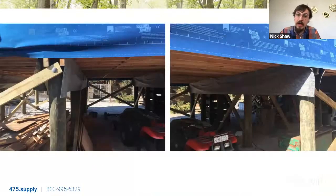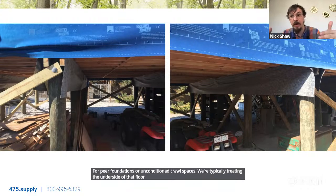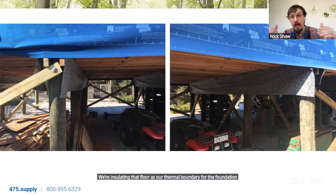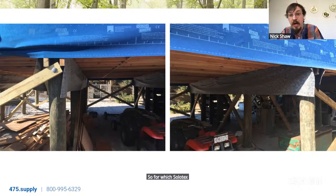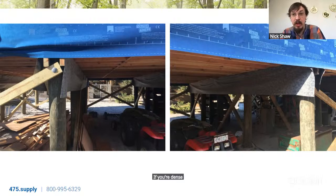For pier foundations or unconditioned crawl spaces, we're typically treating the underside of that floor system as our air barrier. We're insulating that floor. That is our thermal boundary for the foundation. And then we're running really a house wrap on the underside. So for which Solitex Mento membrane is appropriate, it's mainly probably going to be Mento 1000 if it's a batt insulation. If you're dense packing, it would be the Mento Plus.